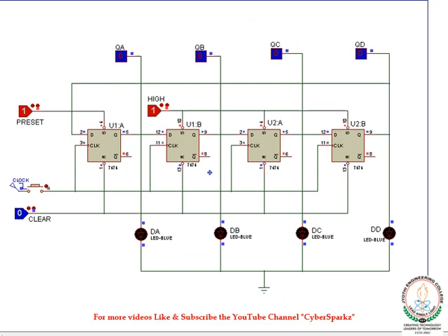Here, in order to check the asynchronous inputs, they are split into 2 sets. For the first flip-flop, we have provided a separate connection, and for the remaining 3 flip-flops, we have a common connection. This first flip-flop alone we are going to set in the ring counter. So this set condition will be transferred to the next flip-flop on obtaining a clock pulse, and this process will be continued. So let's check the asynchronous inputs first.